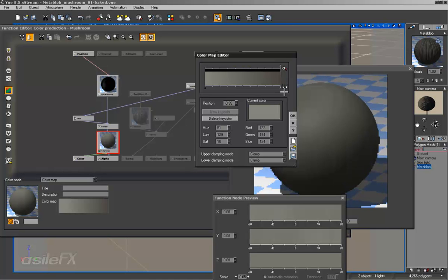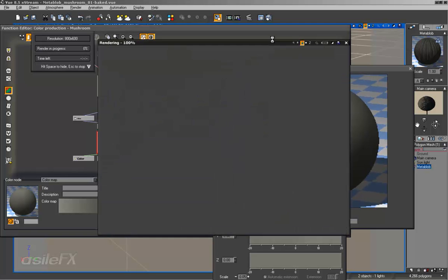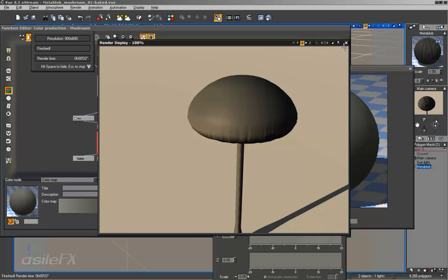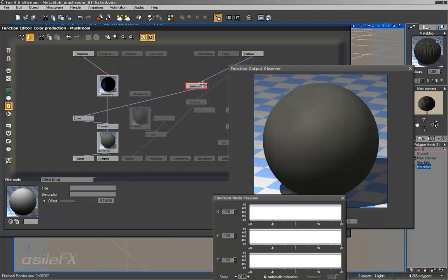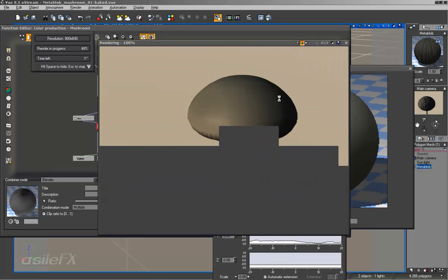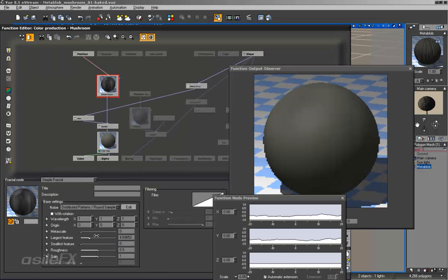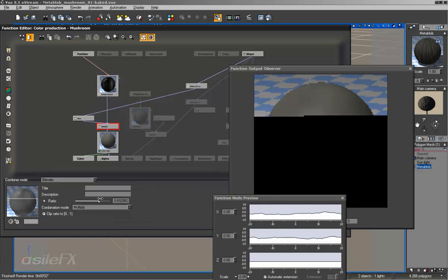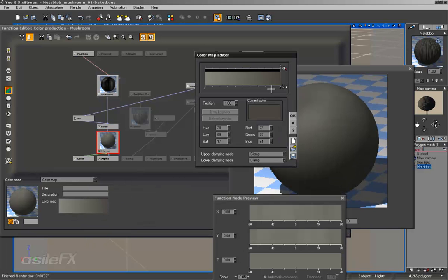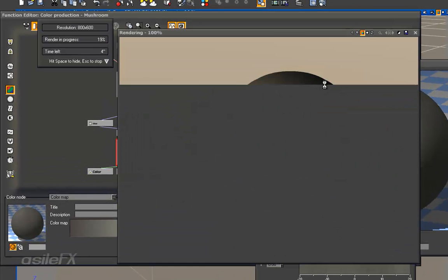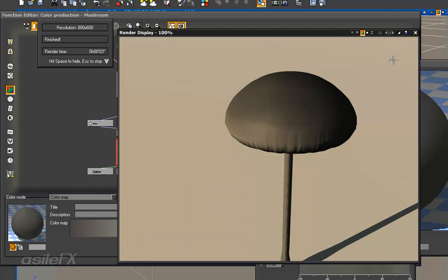One problem when you're swapping is the points do tend to get hidden on the edges, and that's where that line was coming in before, really causing the look of the surface to be a little weird. So it's starting to get a little bit better. We'll go ahead and reduce the scale of the fractal. Increase the gain a little. Maybe swap that back. And I think we're going to stick with that.